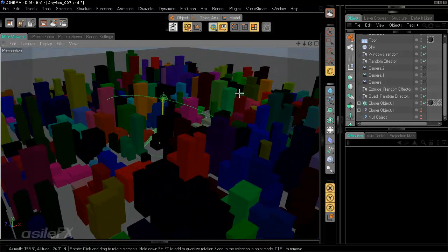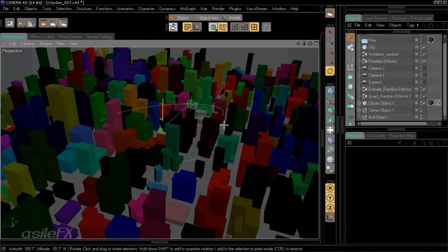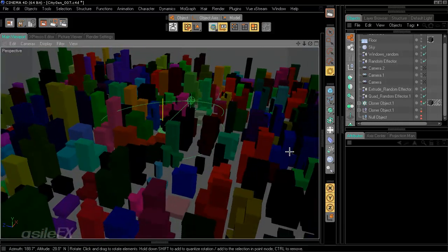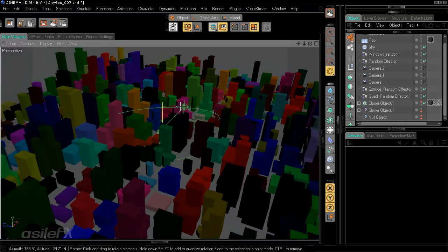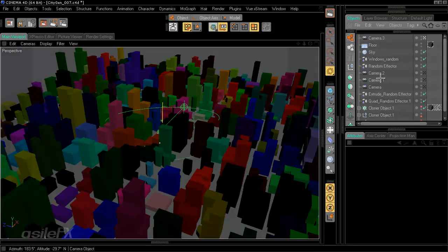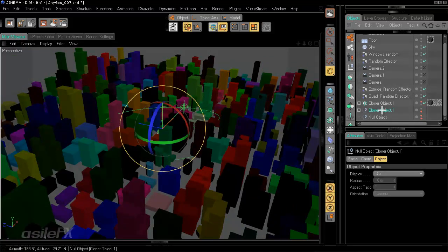Now the other option that we have is to perform a full bake of everything, including preserving all of the textures. What we need to do is use another type of cloner in order to break apart the baked object. But we'll still have the flexibility of being able to move around and navigate the scene just as we do right now. It does require a little bit more setup, and we also won't be able to use the current object that I just set up for our preview, because there are a few steps that need to be taken in order to preserve our polygon selection tags.